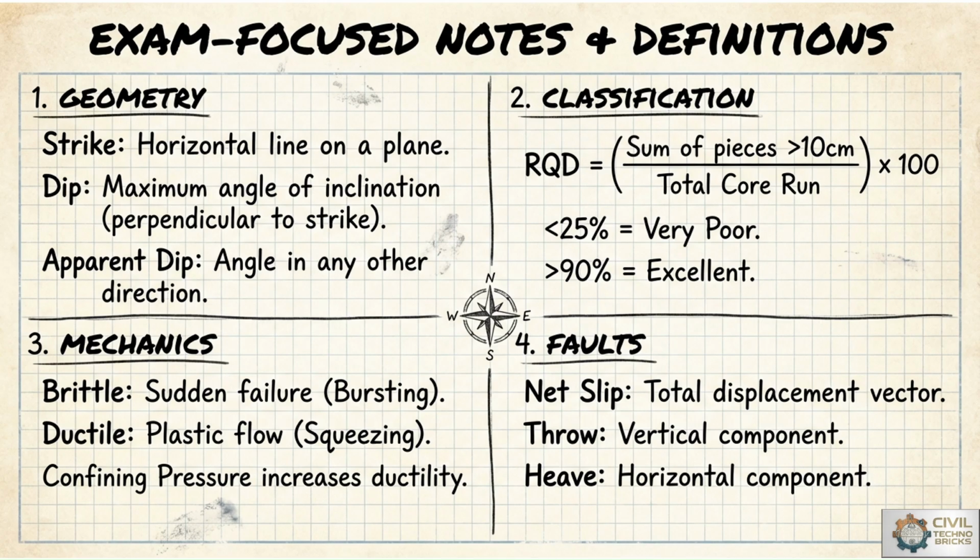Geological investigation guides us for alignment selection, excavation methods, and support design. Engineering geology plays a major role in minimizing construction hazards through the water, the stresses, the strain, the fractures, and operational risk. Proper planning and investigation ensure the durability and sustainable tunnel infrastructure.